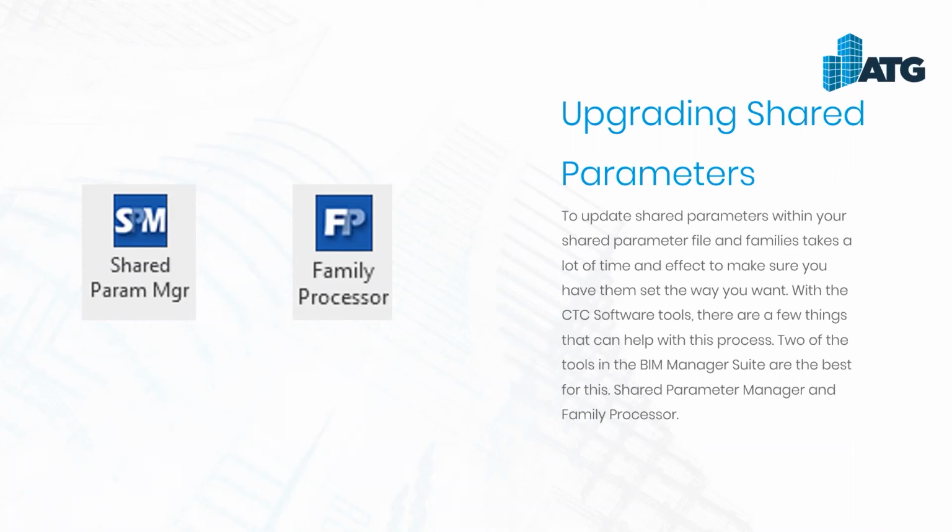Upgrading your shared parameters, again, can take a long time. And if you do not do it properly, you can mess up your shared parameters. In Revit, modifying the shared parameter files within Revit is not really a good way to do it. It's time consuming in there. Once you create a shared parameter, it's stuck. Moving it around is very difficult and cumbersome. And if you have multiple shared parameter files, that's even worse within Revit, because now you have to get it from one shared parameter file and put it into another.